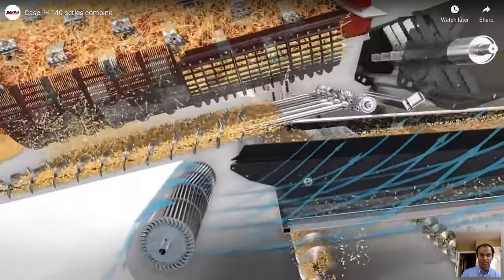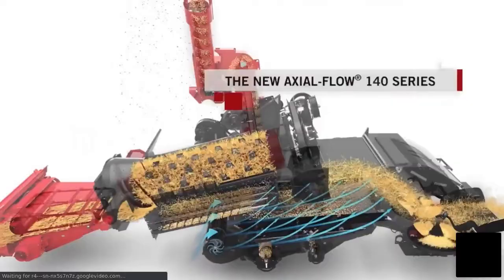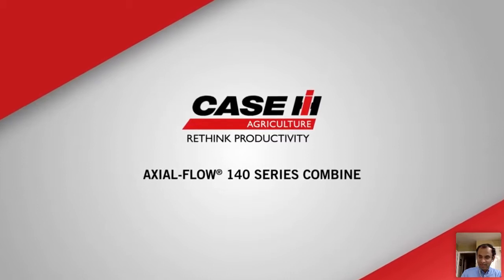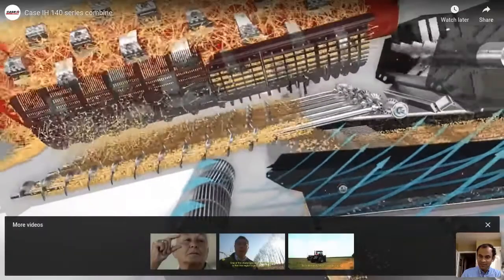Right there, the grain falls into a sieve, and there are multiple sieves. There are 3 sieves: a pre-sieve, a lower sieve, and an upper sieve. They will gradually fall into the 3 sieves, and then the clean grain will fall into the grain bin. And there is a fan to blow out all the chaff.